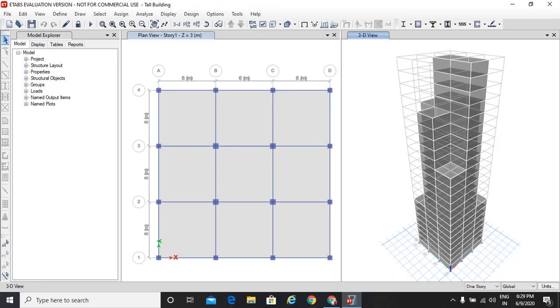Today I am back with another project, the seismic resistant building design. Here we will be defining the seismic loads, analyzing them, and doing seismic analysis using the response spectrum method and the time history analysis method. We will be using the same 23 story tall building that we designed in the previous project. We will first unlock this model, and it will erase all the analysis results from the previous project.